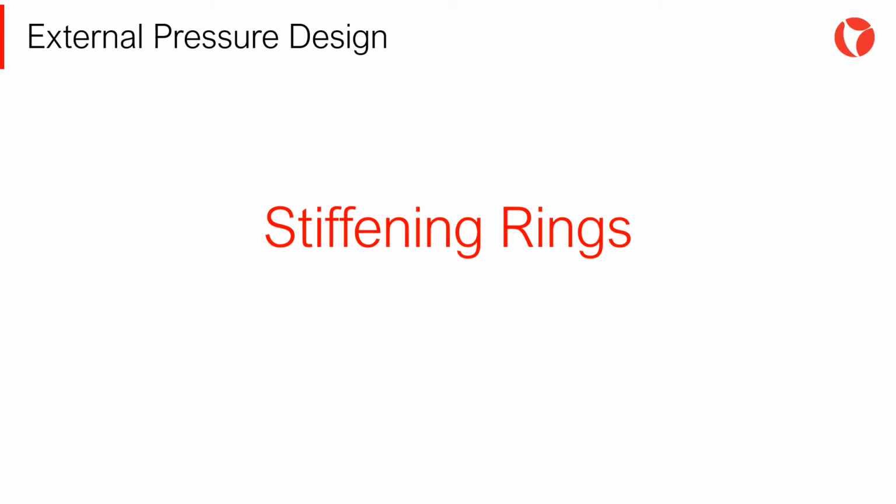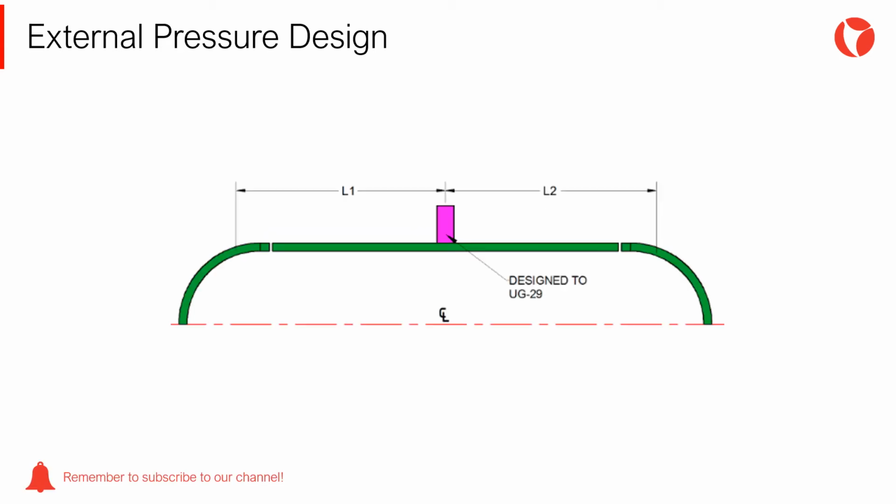External or internal stiffening rings constitute a very good alternative for the vessel to withstand the external pressure requirements. Shortening the distance between support lines makes the vessel's shell more stable. The simply supported beam is shorter this way, thus more resistant to external loads.